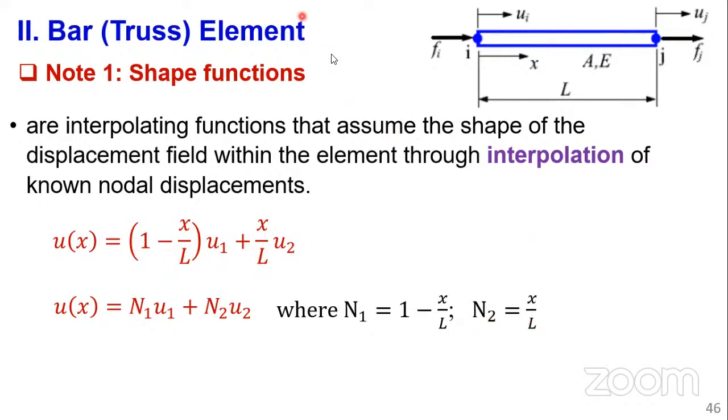And as you can see here, if we try to sketch this, because you may be told to sketch something like this. So if you are to sketch first the shape of the displacement field, this is the displacement, right? So the sketch in itself will be something like this. This is U1, and it varies linearly, and you know it's increasing if it's tension.